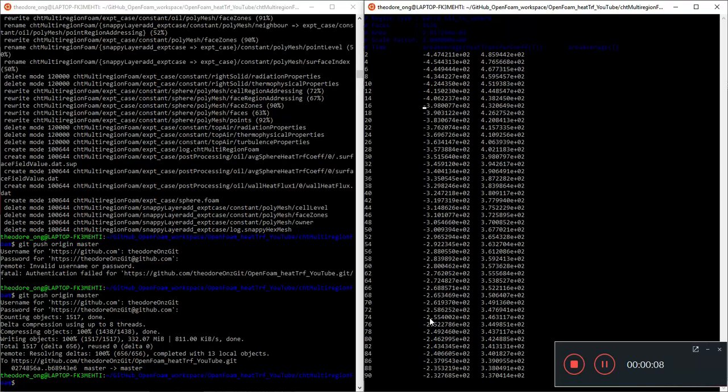We are doing the hot sphere in oil case, and we're trying to validate it against empirical correlation. It was found in the last video that the source of the bug I've been trying to find for the last tens of videos is actually a round-off error in the thermophysical properties. That was explained in the last video. So these are more of the results of comparing this new